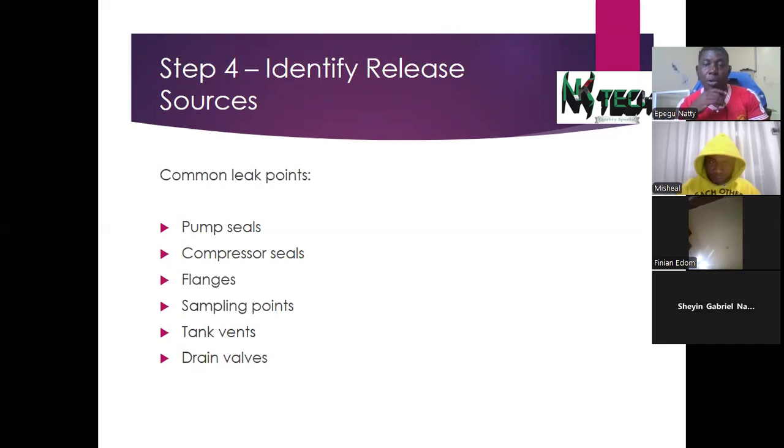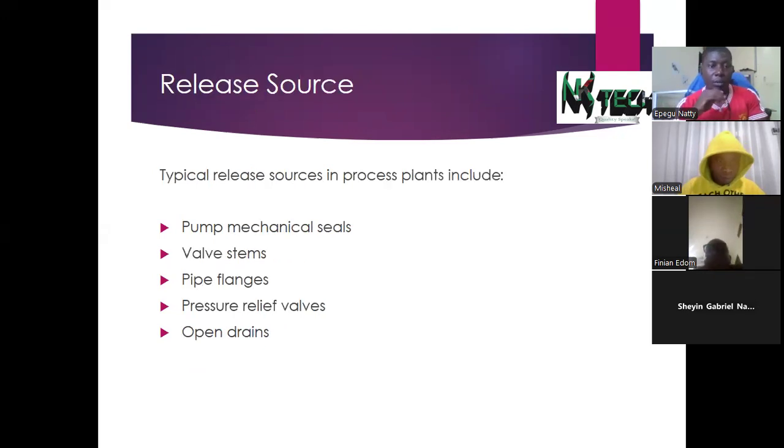And then we also have your drains, right? So your drains, most times during operation, you tend to open some drains for some vessels just to allow water to come out. While the water is coming out, it is bringing out gases and vapors also. So that can also lead to explosion or accident. Okay, so the same thing as your release source. I think we talked about this.